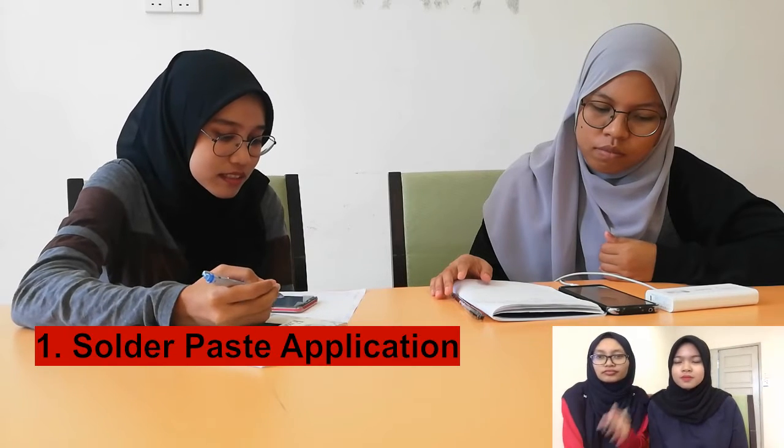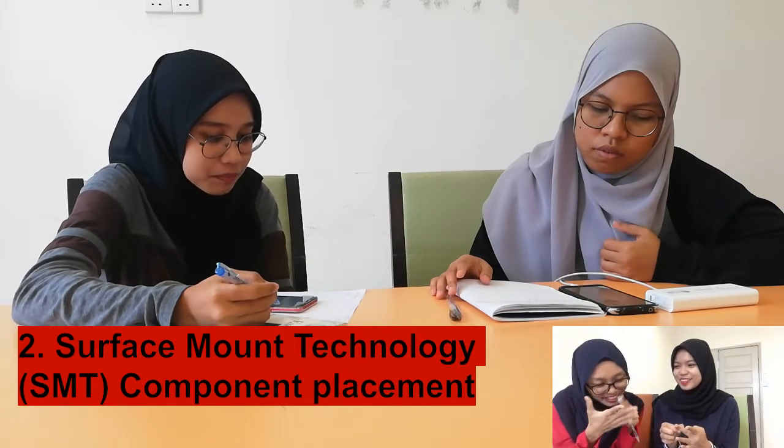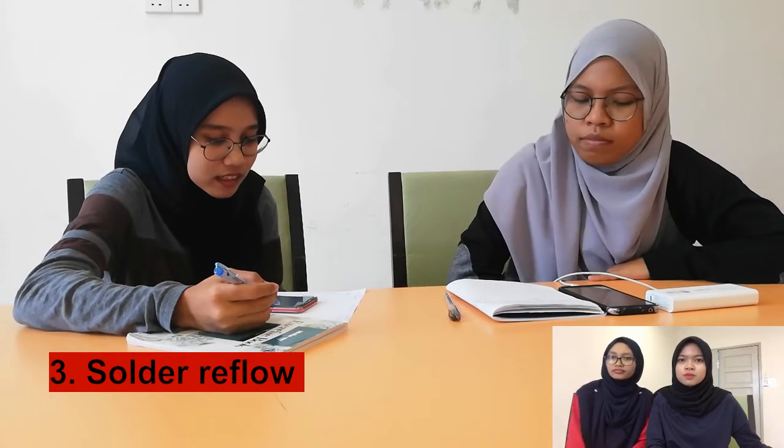The second step is surface mount technology, which is SMT component placement. Here the surface mount components are placed. The third step is solder reflow. In solder reflow, after component placement, the solder is heated and the connections are secured.